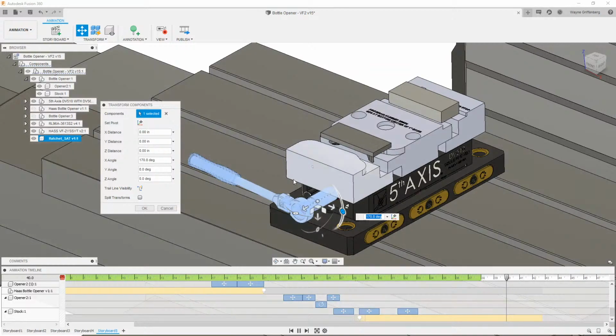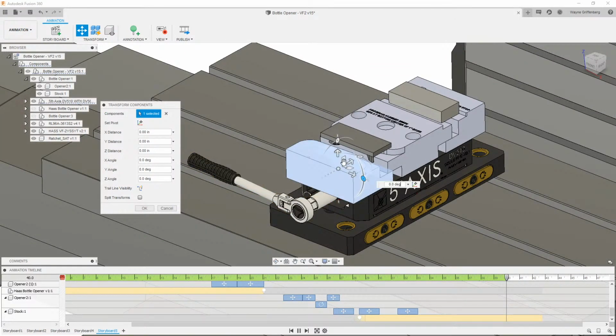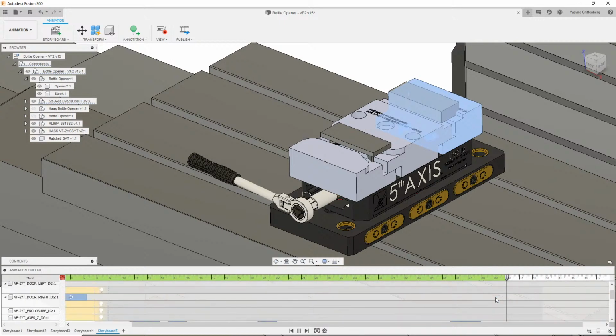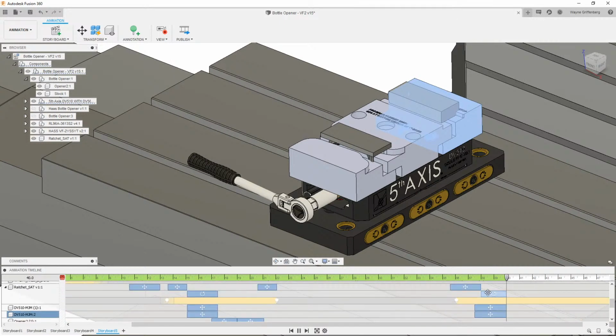170.8 works for me. And at the same time, we want to move this jaw in by a 1/4 inch. Well, it looks like it's reaching pretty close to where I want it. We can move it up, wherever it's going to be. We'll grab this one. I don't think I had it in the right position to start with, but we're going to move this also a 1/4 inch this direction. And again, have your assembly set up exactly where the components are going to be. At the same time, I'm going to say OK. So we have that transition recorded, rotation, and moving those jaws.